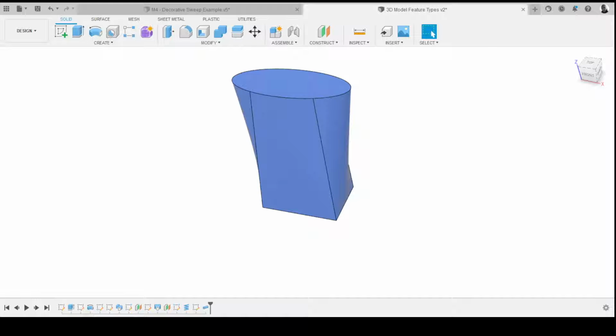You can also create guide rails as well to define the outside or the external shape. You've got to think a bit like you're creating a wireframe of the shape that you want, and then Fusion's filling in the gaps to make a smooth shape. And it'll always try and make a smooth, curved, blended shape. It's not going to make angular shapes within this lofting process. So it's always going to try and blend them and make them smooth by and large.